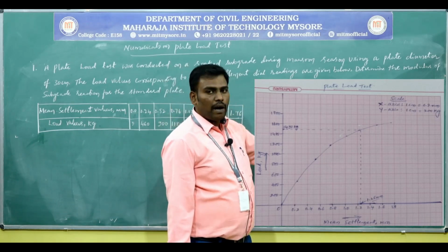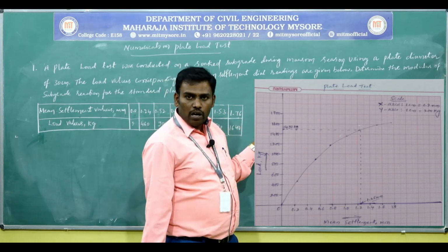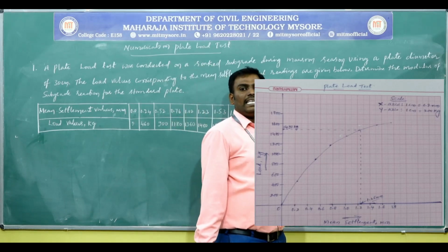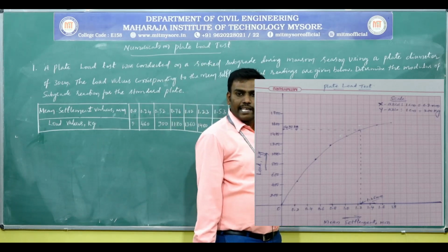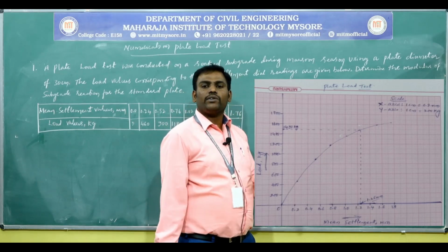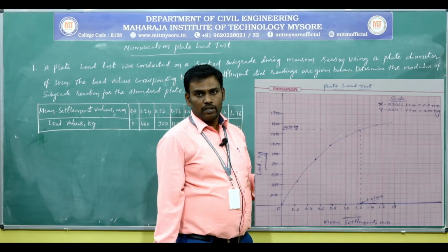From that point you draw the horizontal line, parallel to x-axis which touches the y-axis at a point, that is the load corresponding to 1.25 mm or 0.125 centimeter.